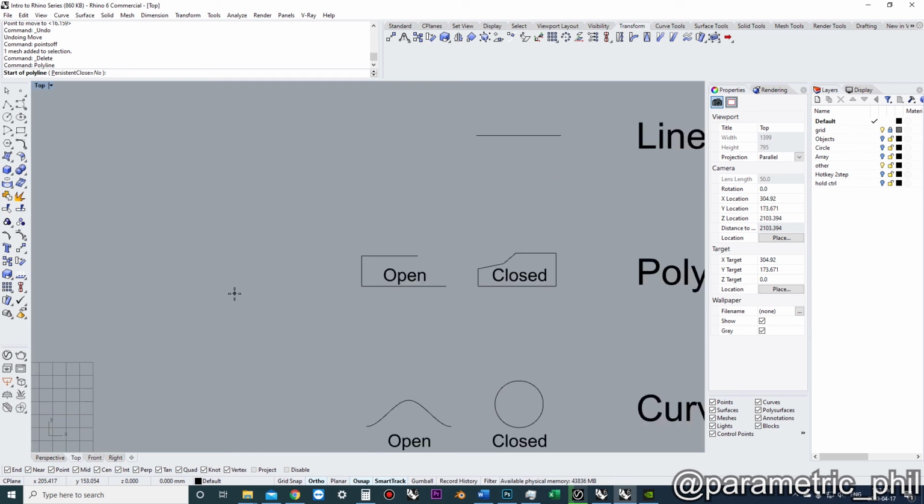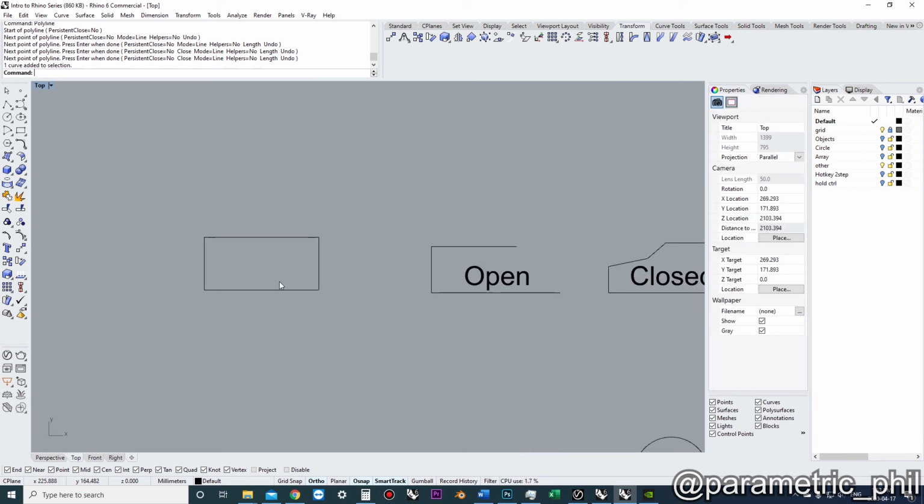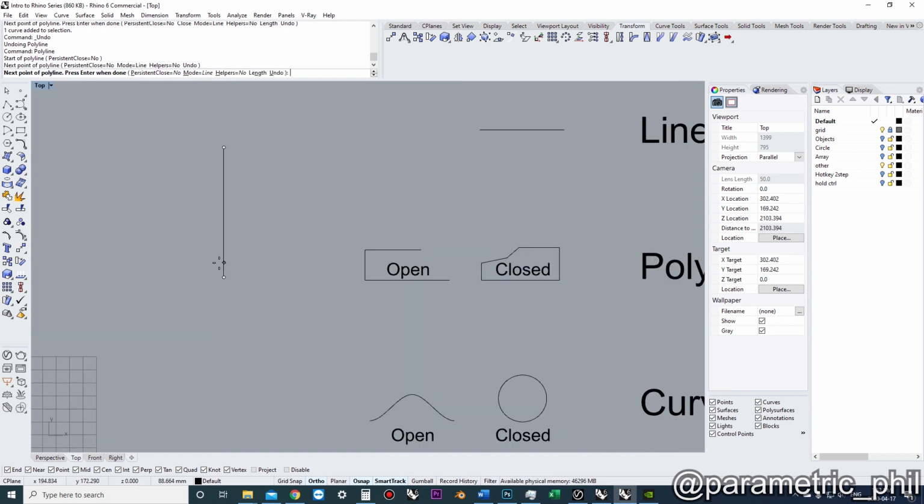And there's a few methods you can use to actually start drawing your line. You can start clicking, and if you have reference points, you can use those reference points to just click and make your drawing. Or you can go in here and you can start typing in dimensions. So I can just type in 100, and then I've locked in the dimension, and I can pick the direction, and then I can go 100 or 50. Okay, and then I can go 100, and then I can close it, or I can click close curve.